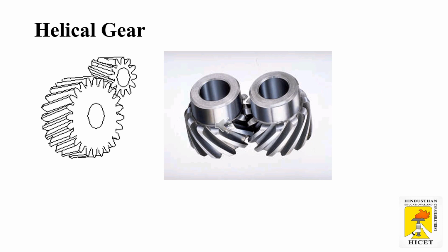Because of the smoother operation, helical gears are preferred in high speed and high load applications such as turbines and heavy vehicles. Since the teeth are inclined to the axis of rotation, helical gears are subjected to axial thrust loads and bending couples.